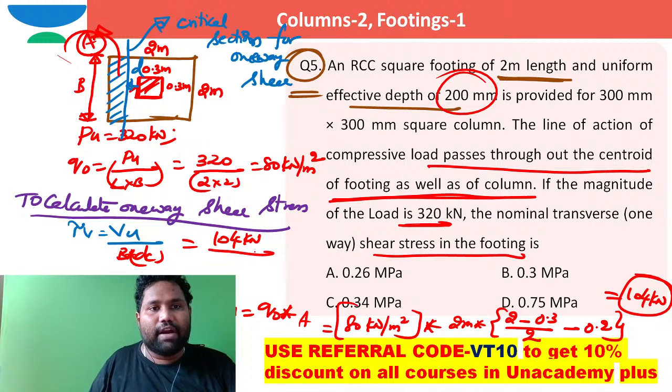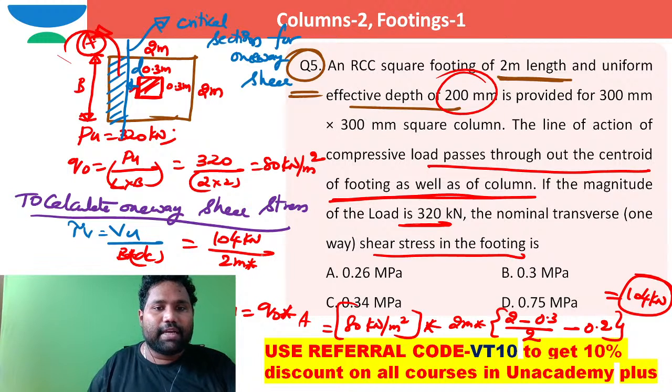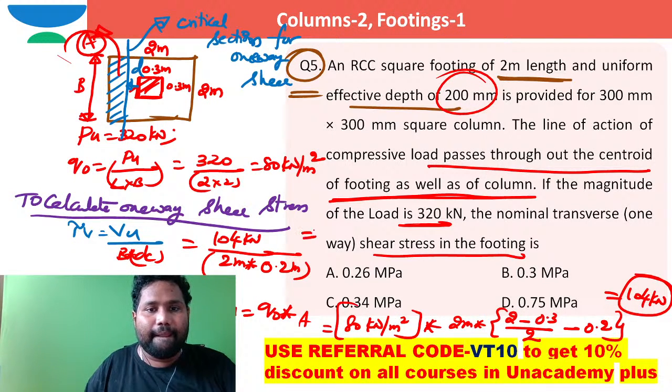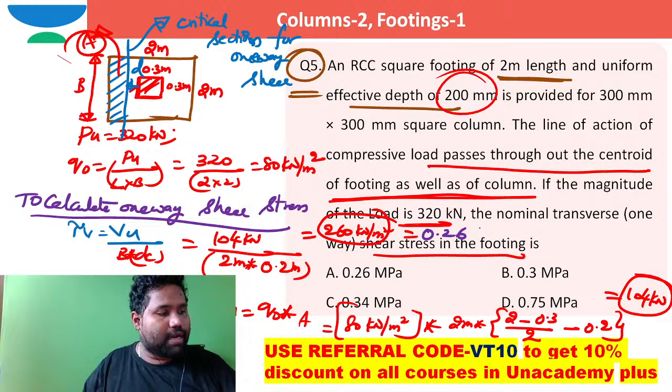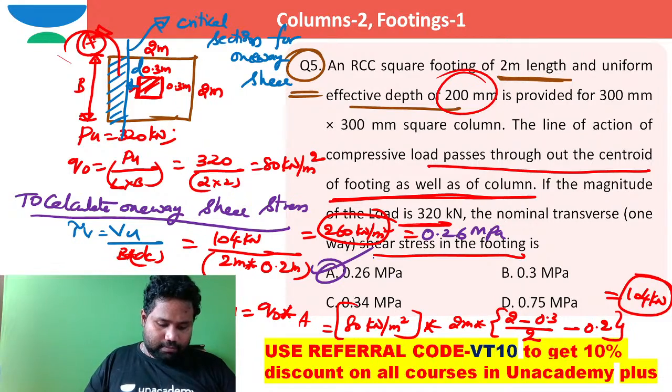Vu is 104 kilonewton, divided by B, which is 2 meter, into d. It is the effective depth of the footing at the critical section, which is 0.2 meter. So in this case the answer will be 260 kilonewton per meter square, that is 260 kilopascal. There are no options in kilopascal, everything is in megapascal, so I can write 260 kilopascal as 0.26 megapascal. Option A itself is the correct option.